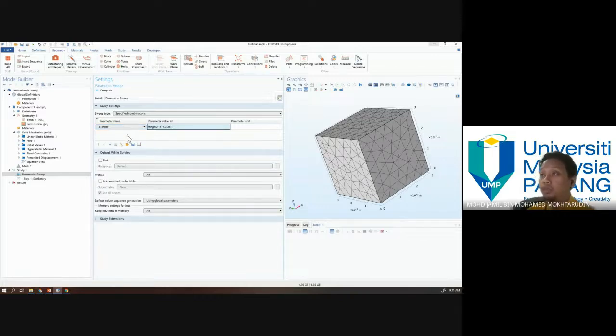Similar to assignment number 4, if you try it later, the question asks you to change the location of the ground electrode. So you can use parametric sweep instead of using multiple consoles. And when you want to plot the result, you would have to take each result from the different simulations and combine them, which is troublesome.